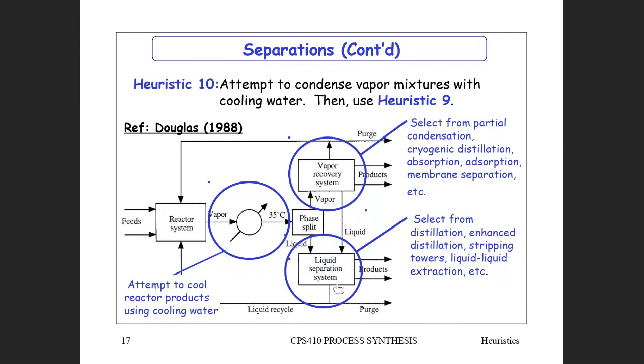The batch reactor might operate at 35 degrees C, where yeast is the most productive, so your fermenter can't go above 35 degrees C. If you lower the pressure of that fermenter, you can strip off the ethanol as it forms, because it will be the lowest boiling component of that system, and you can keep that going.